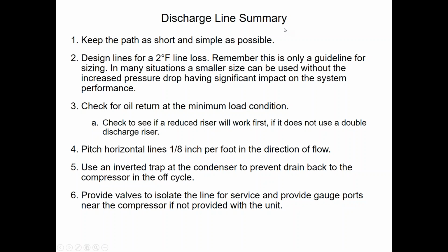All right. Discharge line, going over a summary of it again. Just like the suction line, you want to keep it as short and simple as possible. Short and simple keeps your velocity up. With the velocity up in the vapor, you get better oil entrainment. And just always remember that the vapor state of the gas has a little bit harder time entraining the oil. There are just not as many molecules of refrigerant, if you will, to adhere to the oil and then entrain and bring it back. Okay, so vapor is always your challenge. Liquid line, that's got no problem bringing oil back at all. So, all right, short and simple.